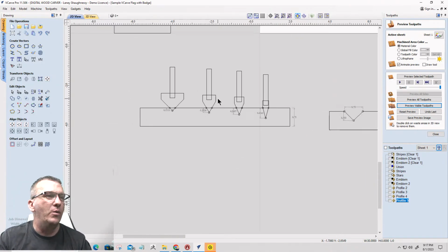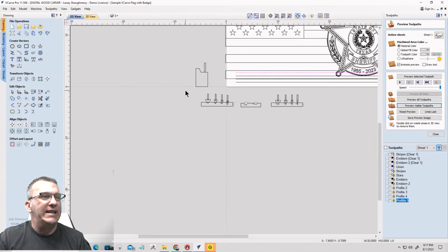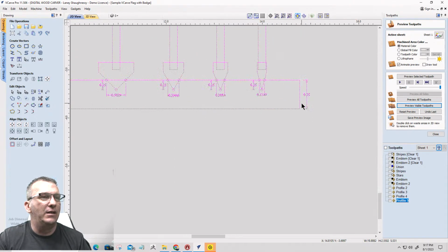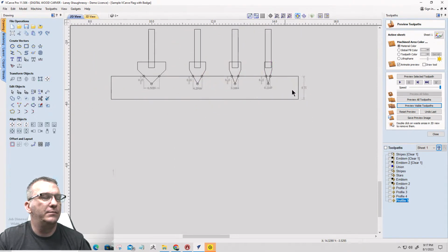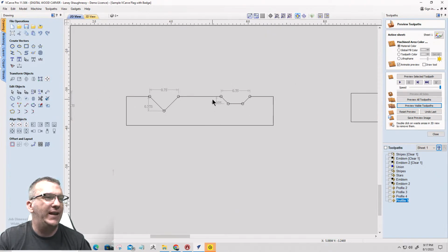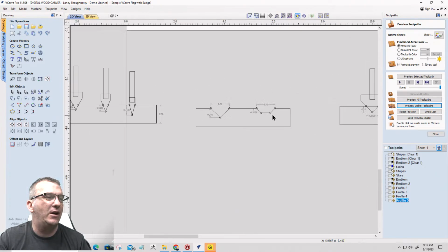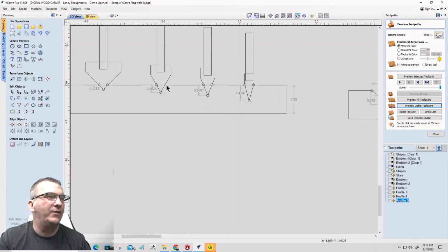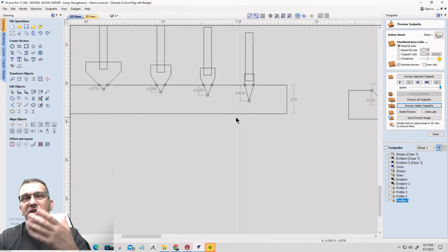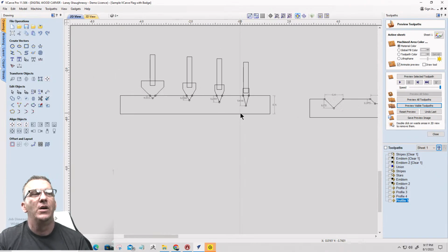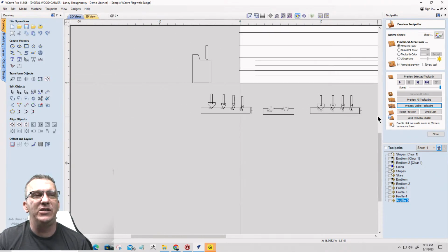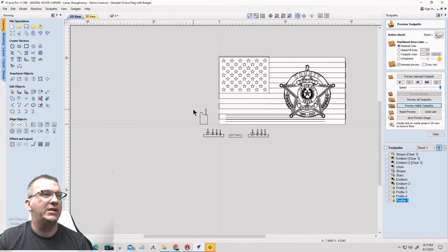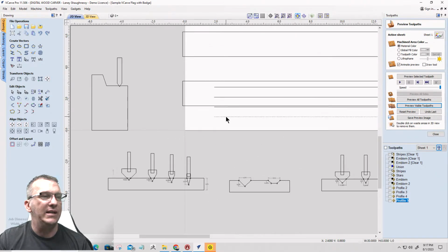All right, so hopefully that little explanation of profiles and flat depths, full V-carves, and how the angle of a bit changes the depth of cut on a V-carve helped some or gave you something, again, food for thought, right? Something to think about. All right, let's go ahead and get rid of these lines.